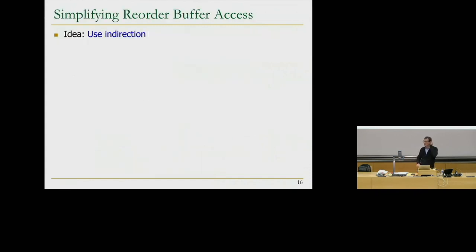Yes? So the reorder buffer holds the youngest values of this register. But yeah, if you search for a certain register, you take the oldest. No, you need to take the youngest one. You're just fetching this instruction. You need to take the value that's produced by the latest instruction in the program, right?